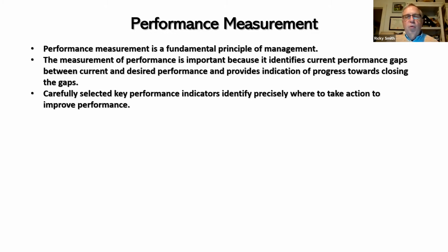But what action would I take there? If I have high emergency labor hours, maybe I need to look at my preventive maintenance program. Maybe my PM program is not effective. So if I improve my PM program, I can improve performance overall. So PM compliance, but also my emergency labor hours, are important to me.